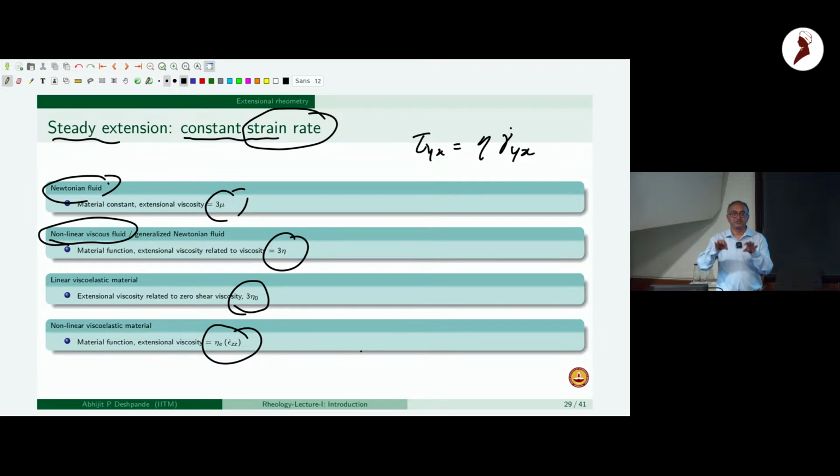So I am actually processing the fiber not by pushing it out of the capillary, that's one part of it, but the real processing is happening, and the final dimension is being determined, by these stretching flows. And whether I get a fiber with uniform diameter, or there are instabilities, or can I predict what rate I should rotate this at, I need to know the extensional viscosity, so that I know what roller torques to use, so that I'll get a speed and so on. So polymer processing is one example where you would definitely need to know the extensional behavior.